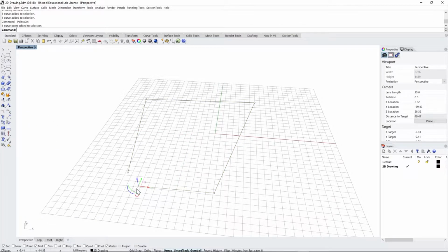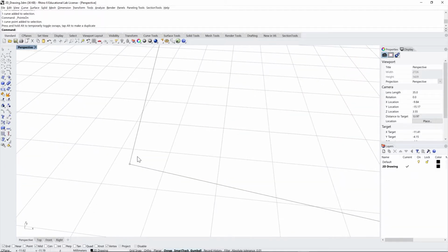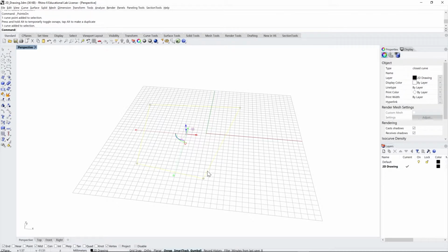we can make use of this property so to move the end point to the start point of the polyline. By doing this, we first need to check that we have the OSNAP activated by the endpoints. So it's going to be just much easier to do the connection. And now if we select it again, we see that it's a closed curve.